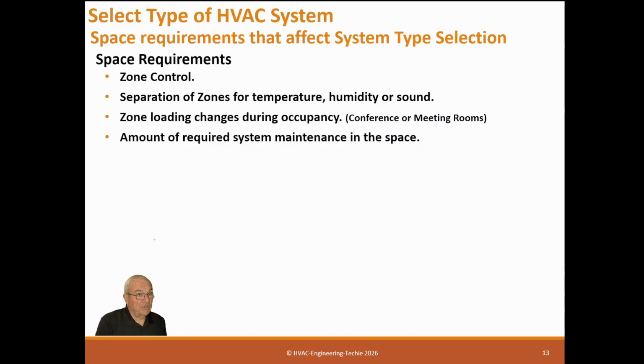This is an owner's requirement. If you put hydronic heat pumps above the workspace, then for people to change the filters, they've got to come into the space with ladders, take the ceiling apart, go above people that are working. For some occupancy, this is not an acceptable choice. Sound and vibration levels in the space. We normally don't find this out till after the fact, but designers, you're responsible for designing a system with low sound power levels, and all the manufacturers list the sound power levels of their equipment.